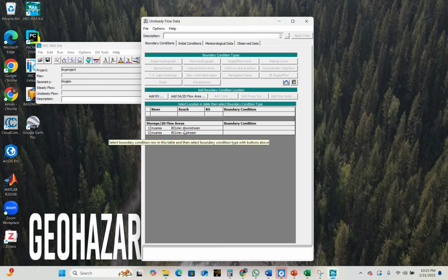As we saw in providing geometry, I provided two boundary conditions. But for example, if you have two outlets, you can produce two downstream boundary conditions. Or if you want to introduce precipitation as a boundary condition, you have to add another boundary condition, and each boundary condition has its own value, and we have to be aware of this point.